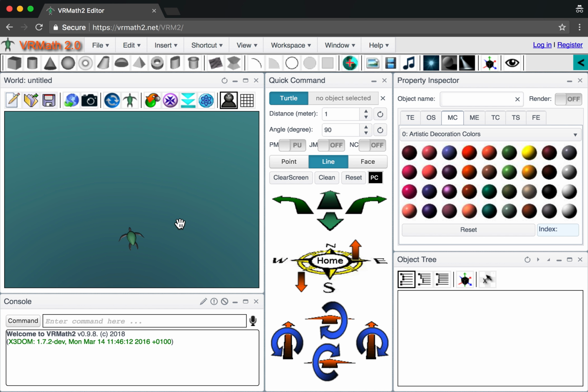And if you hold down the control key and then you drag, then that is called panning the screen to the left and right, if you like. So that is really the examine mode, and you've got to try to use some sort of keyboard or mouse click combination to try it out, how to easily bring things or look at things in the 3D world to a location you like to go to.